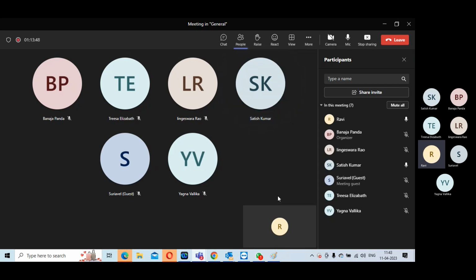Physical cell, yes. In the dot lib, there won't be a dot lib for physical-only cells. You have to understand there won't be any timing or power information except for decap, where there will be leakage information. So LEF and these things will have that physical-only information. And for fill, even in your dot lib when you look at fill, it won't have any logic. It will only tell you the leakage and electrical characteristics present for that.